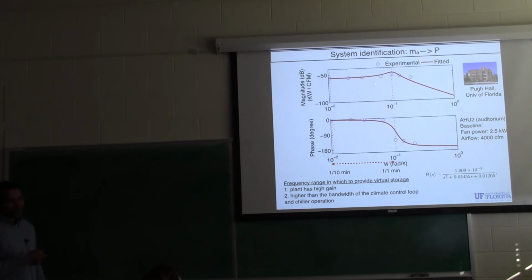It's called a sine sweep experiment. I don't know if some of you might know what this is. You send a sinusoidal signal into the system, record the output, and figure out the gain and the phase. You do it frequency by frequency. You can experimentally determine the Bode plot of the system. So we actually experimentally obtained the Bode plot of the system. What is the system? It's the transfer function from airflow rate to power deviation.